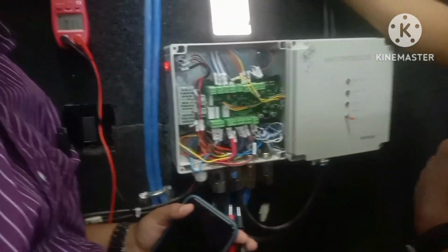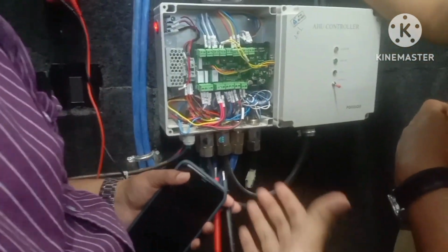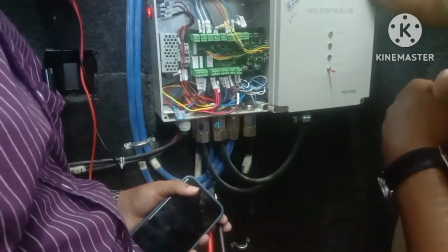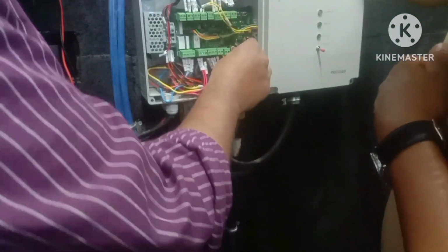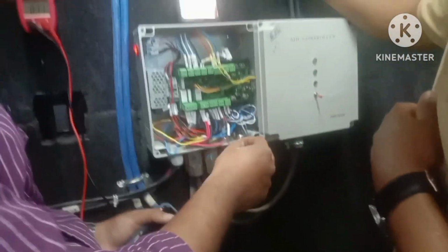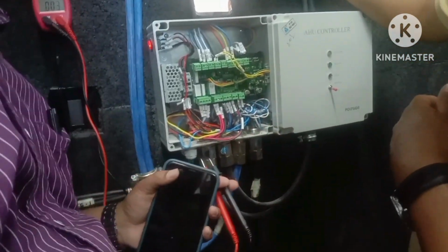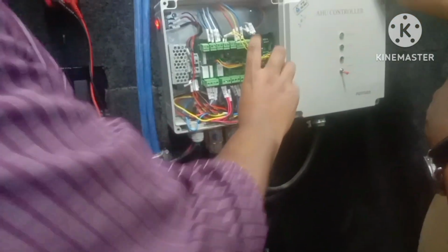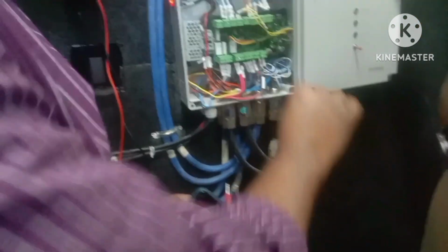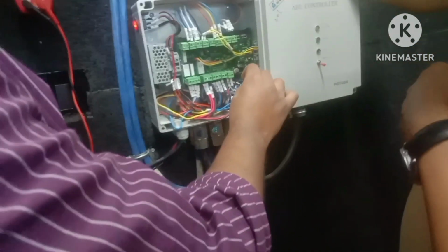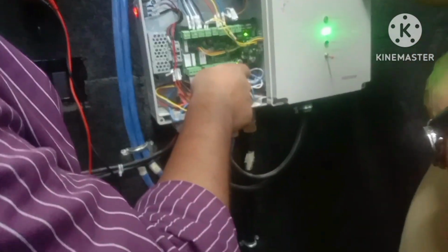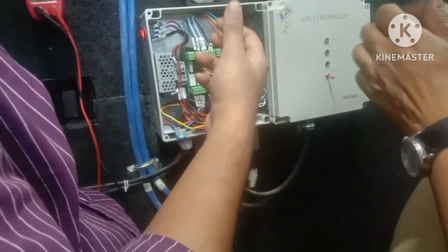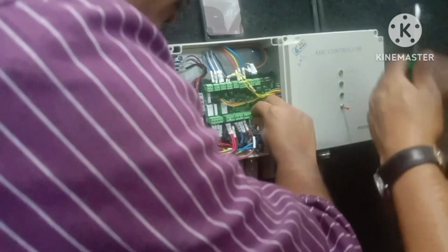Sometimes this condition also can come, as there are a lot of wires, the connector must have come out, or sometimes the connector goes faulty. So after checking on this terminal you have to check on the wires. If that voltage is coming in the wire, then you have to change just the connector, nothing else. Sometimes this connector can also be loose. If there is loose contact in between, the voltage will go out, come again, go out, come again, it's like that.